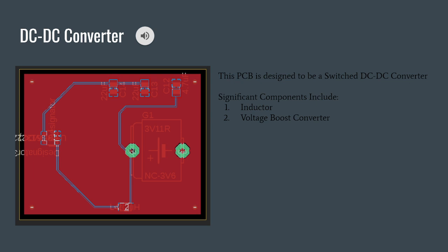Issues so far: the connection with the wall mount and to the microcontroller was the main issue, because the microcontroller only accepted a power supply that utilizes a USB-C type. In our design for the DC to DC converter, there were no ports. At first, it was thought to just connect the wires directly to the port, but we are now designing a future iteration with ports on the DC to DC PCB to install directly into the microcontroller.